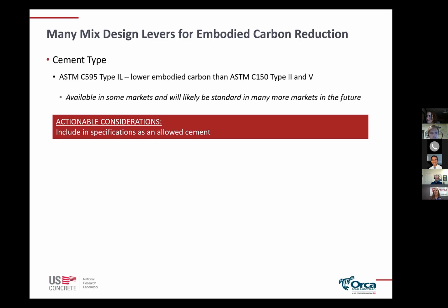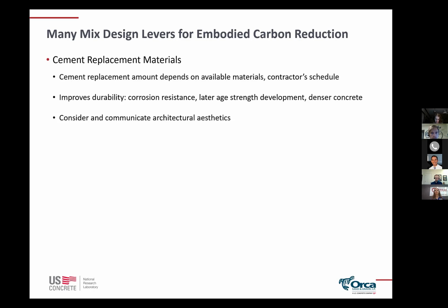And so an actionable consideration here is to just include in the specification the allowance for an ASTM C595 or an ASTM C150 cement. And that starts the preparation for transitioning to having those available.